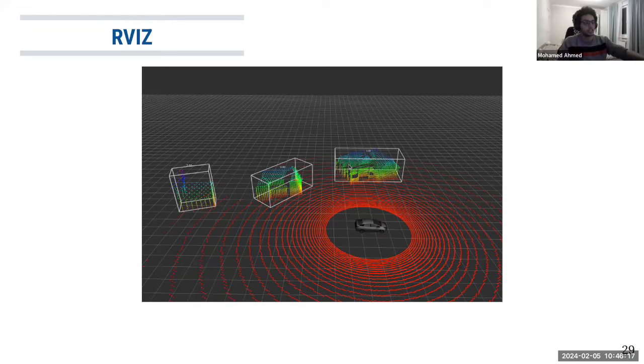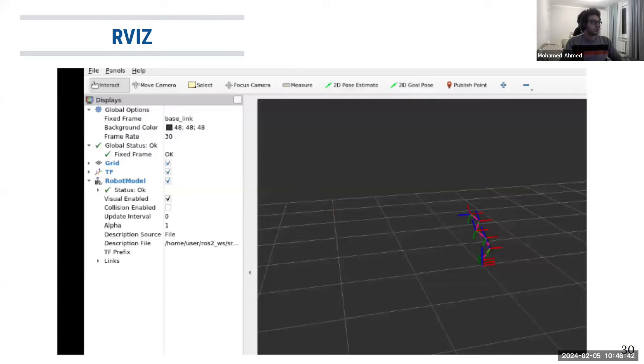And as you can see, you can have a node, for example, that takes a point cloud and passes it through an AI model, and it parses the output, which is the detections, the objects detected as bounding boxes. It can give you the bounding boxes later, and we can show them on RViz as well. It can also show you where each object is located. This is what we call the TF, the transform package. The transform package also has a plugin that can show it on RViz.